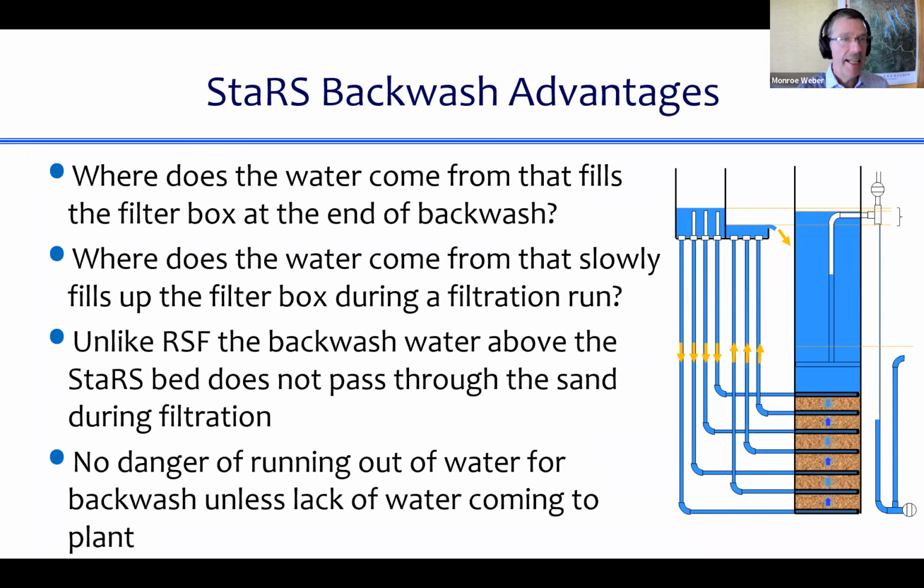This can't happen with a STARS filter because we don't use filtered water, we use clarified water. So that means that as long as there is water coming into the plant and going through your flocculator and your clarifier, you've got a source of water to backwash. Of course, with the caveat that there must be enough water coming in to fluidize at least one filter sand bed.